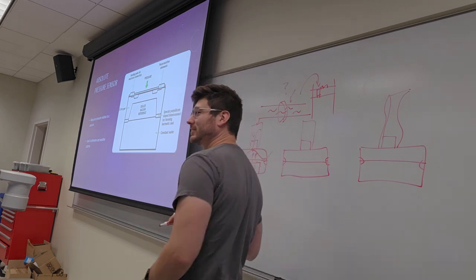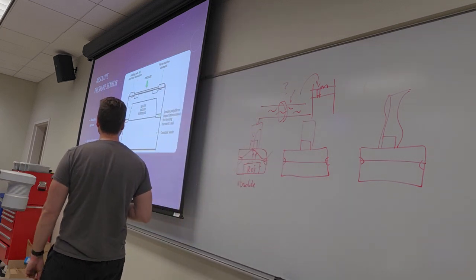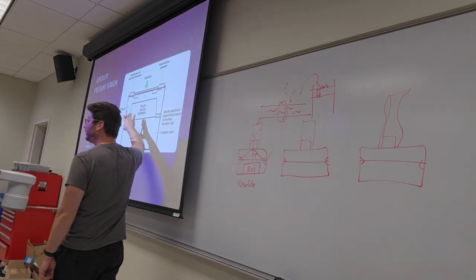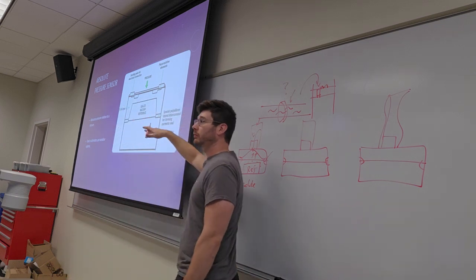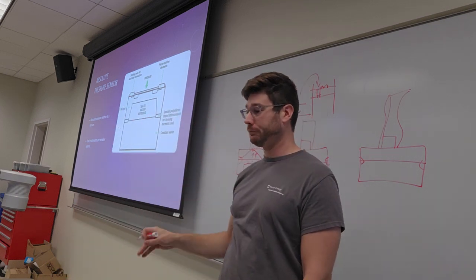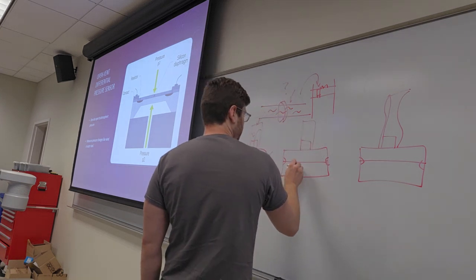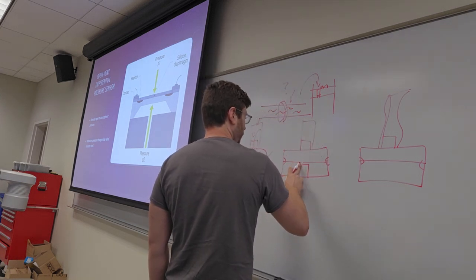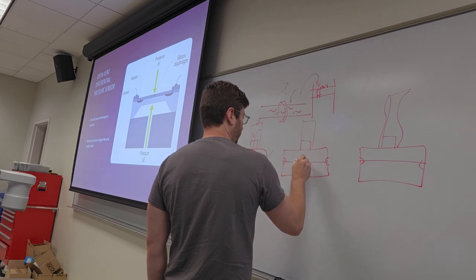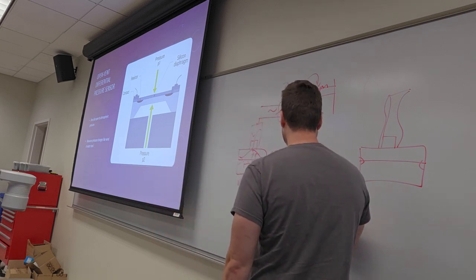Absolute, got it. Okay, with a reference volume inside of it. It's placed there in the factory, right? Factory settings have it be whatever it wants. Sometimes it's filled with argon, whatever. Then we have the open vent. Okay. This is always comparing against the environment of the sensor.